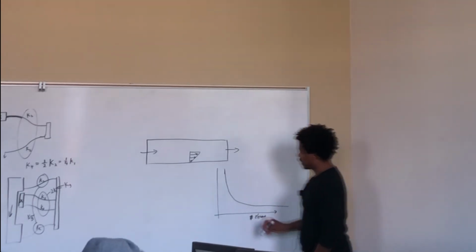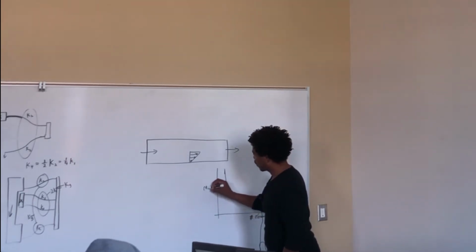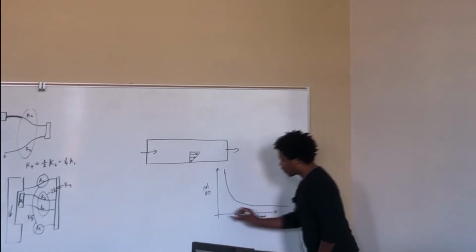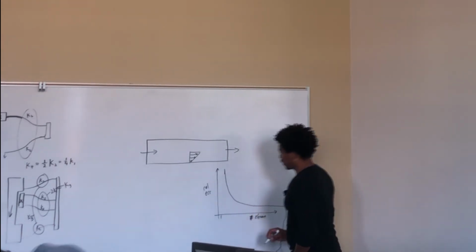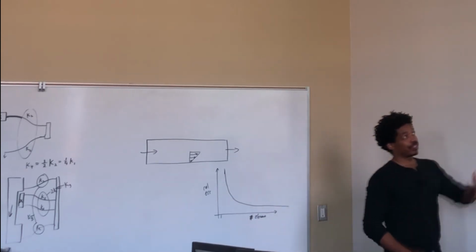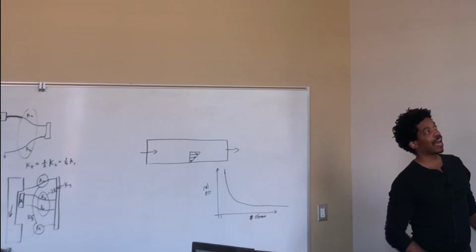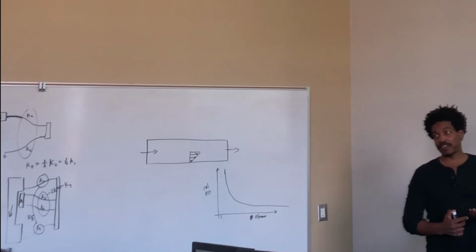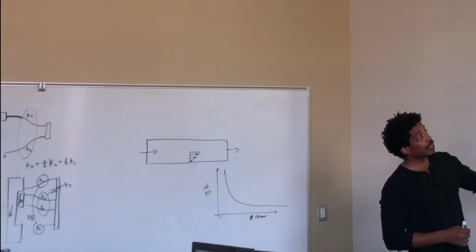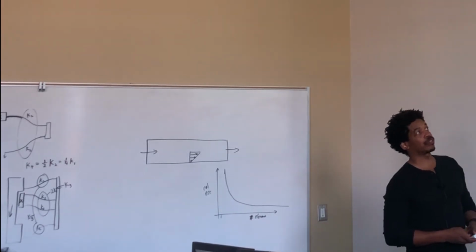Okay, and then this right here is your relative error, in this direction. So if you have one element, and you're trying to show how the fluid behaves, it's not going to be very accurate at all. It's going to be a very poor representation. Okay, but that's a pretty fine mesh, so you're going to have a really good result.